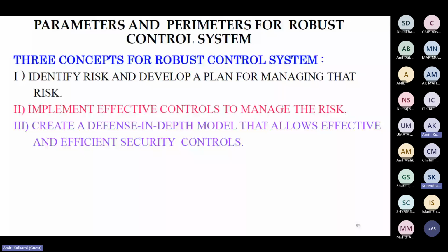As per my plant visit and my observation, I found that there are multiple OEM products, like PLC or Modbus converter or HMI, that use a default password. They don't use a security or complex password. Why don't they follow security compliance?